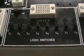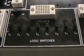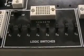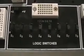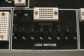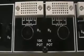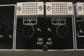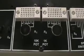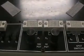The logic switches are also useful for providing a user-defined input signal. There are 8 switches, which can be set to provide a logic level 0 or logic level 1. The value of logic level 1 can be either positive 5 volts or positive V, which can be set at the top of the board. The potentiometers, located at the bottom center of the board, provide a variable resistance. One provides resistance from 0 to 10 kiloohms and the other 0 to 1 kiloohm.